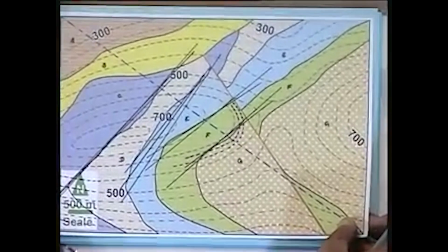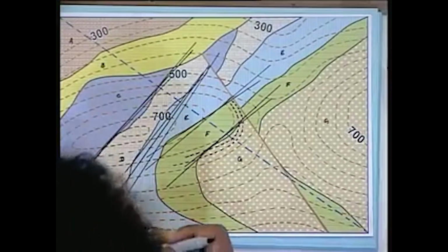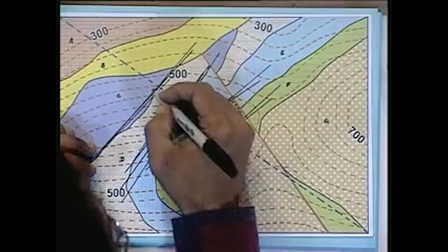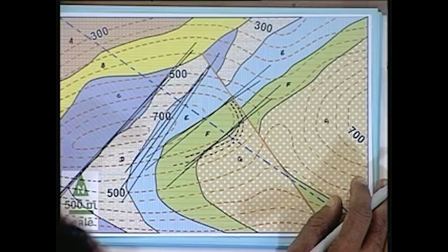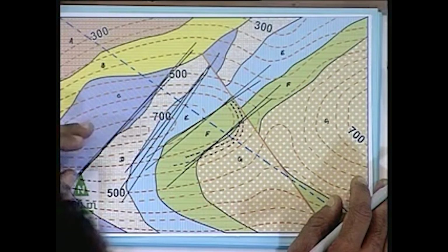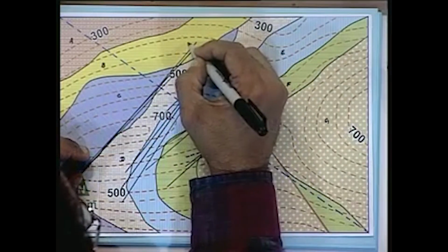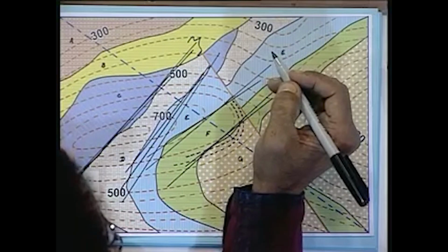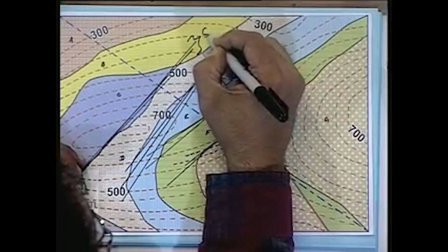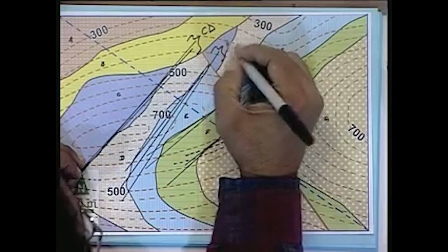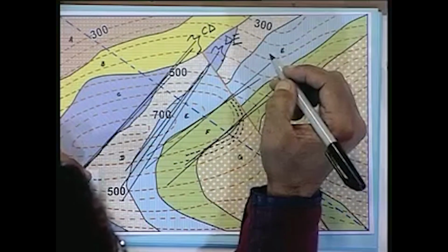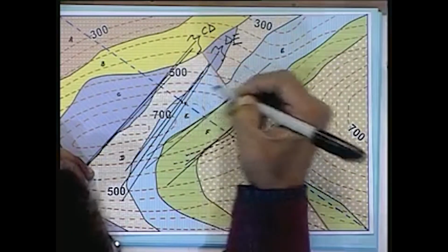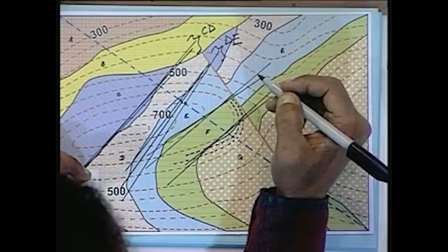So here again we have marked the section lines, the strike lines, and again you have to actually label the strike lines and project the strike lines up to the appropriate values to demarcate the interfaces between units C and D in this case, because the strike lines that are bunching here represent the interface between units C and D, and the strike lines that bunch out here represent the interfaces between units D and E. So you have to appropriately label the strike lines, find out the intersection of the strike lines, and project it upward to appropriate elevation.